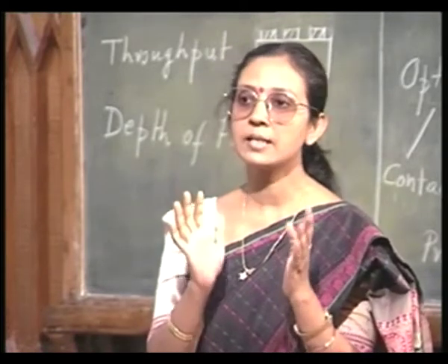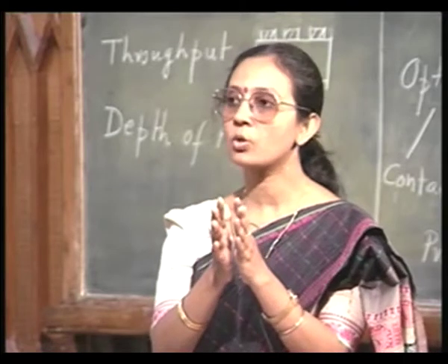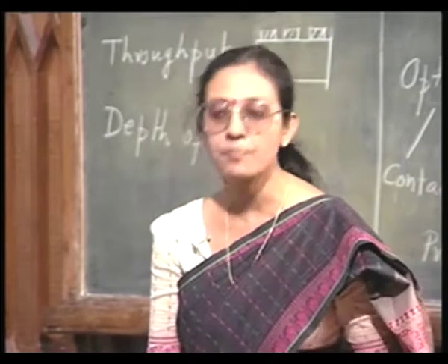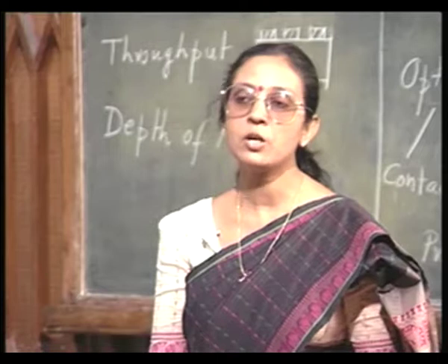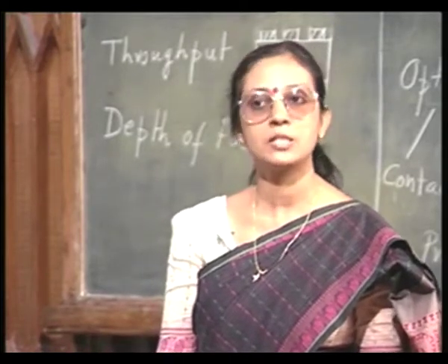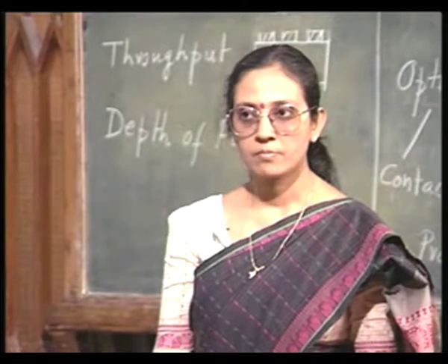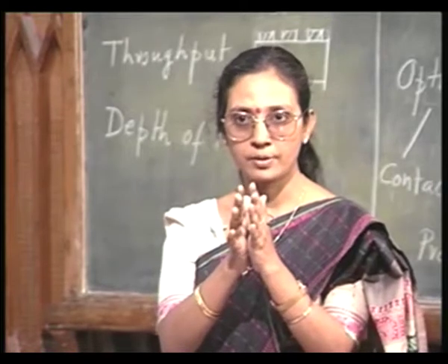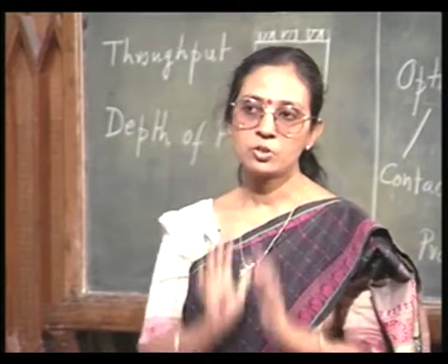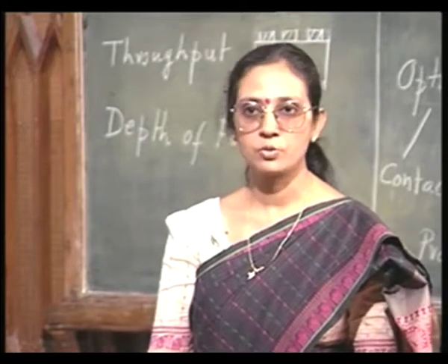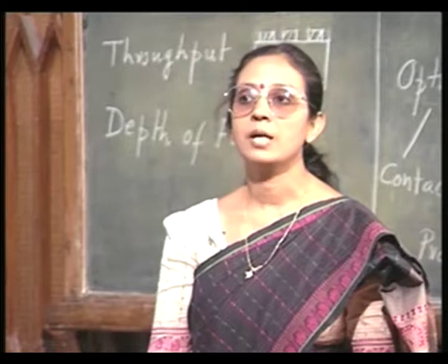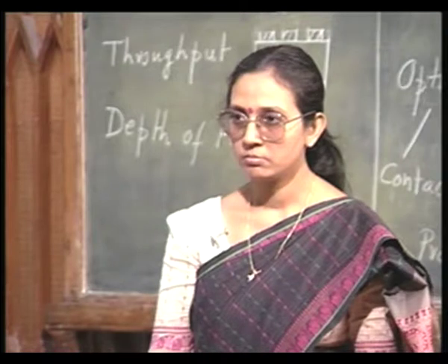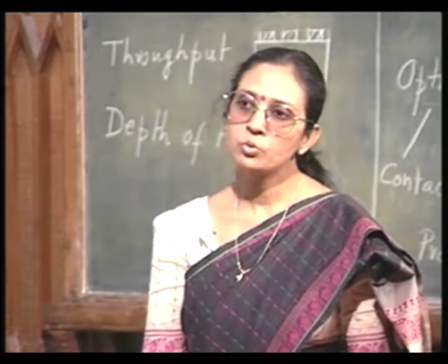Closeness, right? That is, here the mask and the wafer are placed close together, but not actually in contact. There is a small gap between the two of them, which can be of the order of 10 to 25 micrometer. So, you are paying a little bit in terms of resolution, because there is this small gap. But the life of the mask is going to dramatically increase. You can have a resolution of 2 to 4 micron.